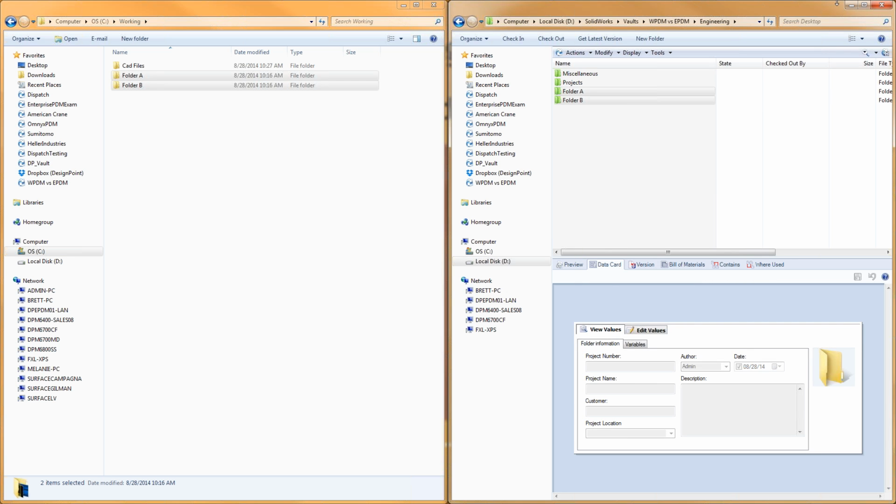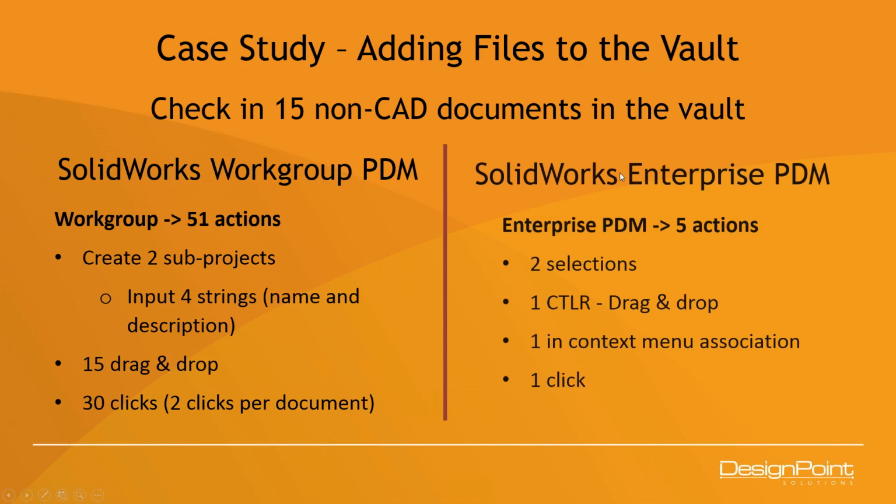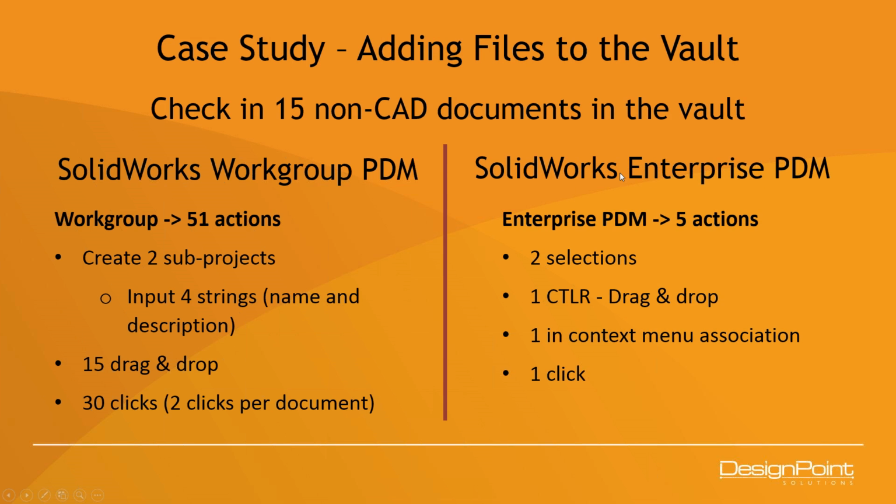So basically, if I go back to the presentation, in SolidWorks Enterprise, I have to do only 5 actions. So basically, I select the 2 folders, drag and drop, right-click, and check in.